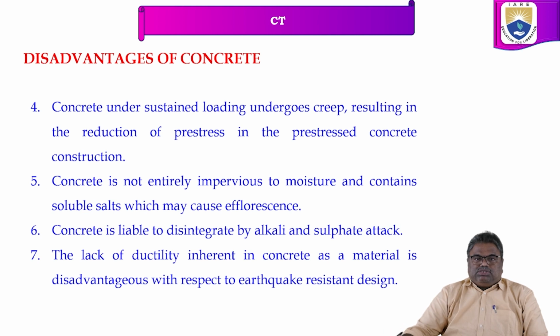The concrete under sustained loading undergoes creep, resulting in the reduction of pre-stress in the pre-stressed concrete construction. So this fourth disadvantage is especially for pre-stressed concrete. The concrete sustains the loading and undergoes creep. So it results in the reduction of pre-stress, and there will be a loss in the pre-stressed concrete.